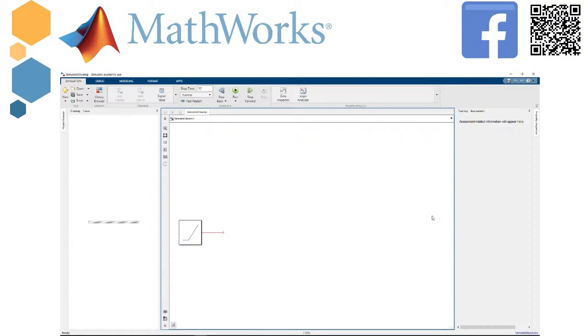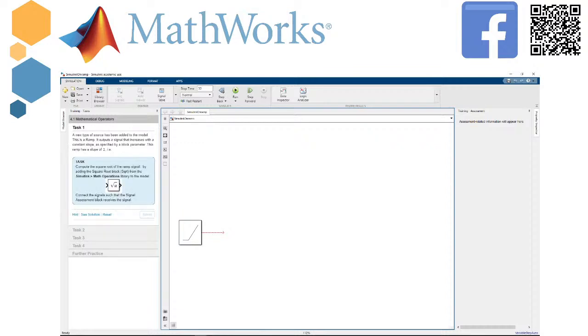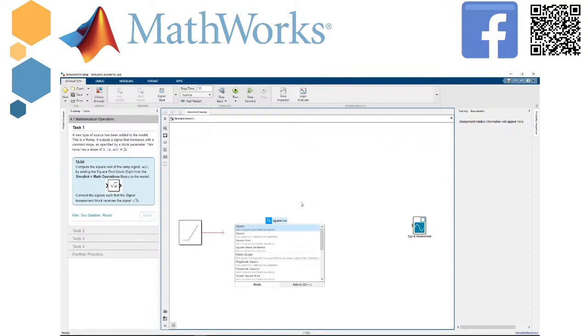I created one. This is our subtraction. What I'm going to connect is 3 with the minus, so before 3 there is a minus, and with the plus, this one. Connect them to the scope block, and it will display the right solution. So what I'm doing is just subtracting 3 from the root. So really easy to write an equation.